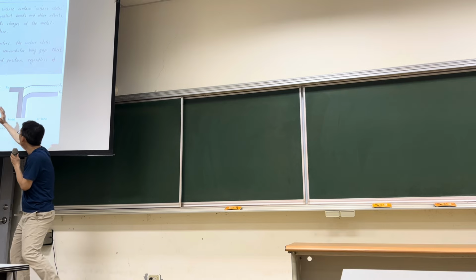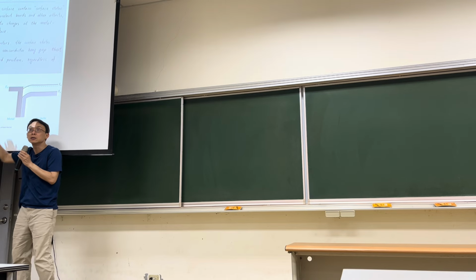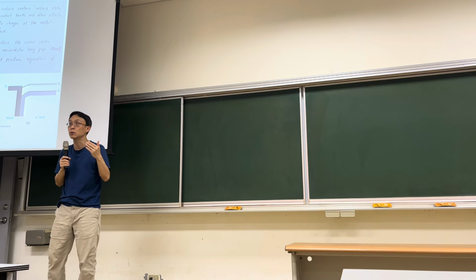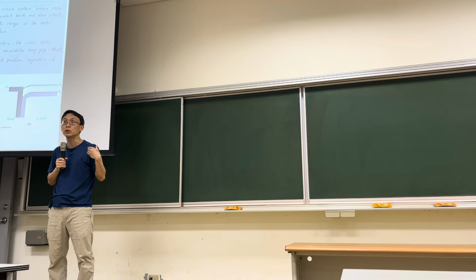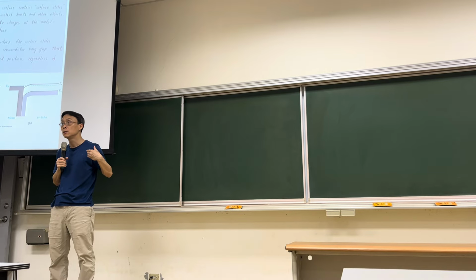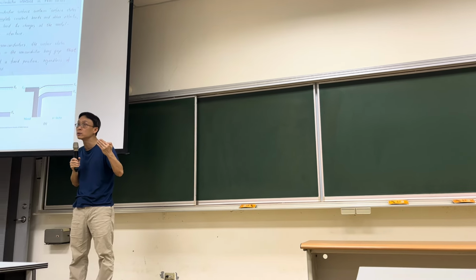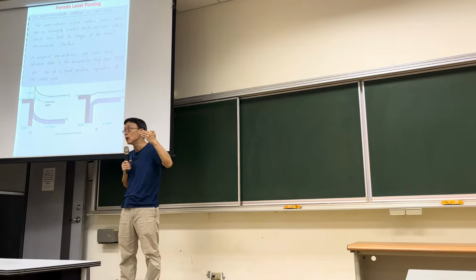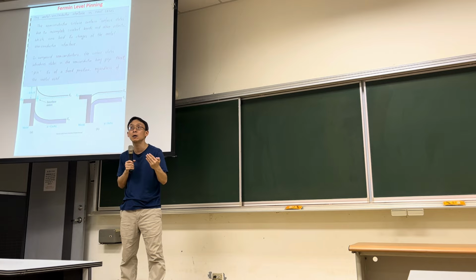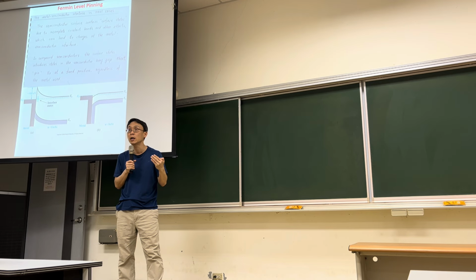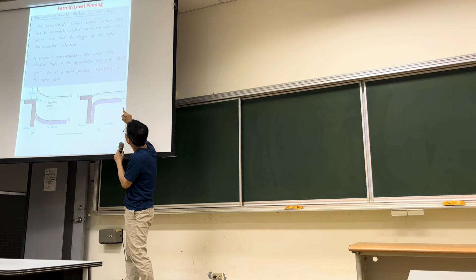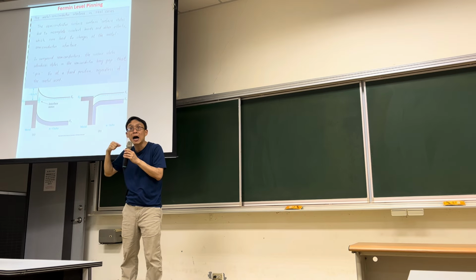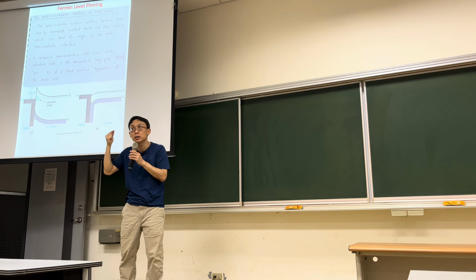Regardless of the metal you choose, this is the special case for semiconductors, which is very important. You want to know this, otherwise you will see some strange behavior, which is the IV curve is always Schottky or ohmic, no matter what kind of material or metal you choose, because that's the result of Fermi level pinning due to the high density of surface states.